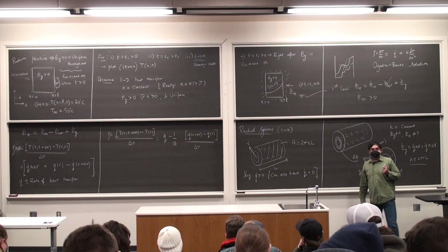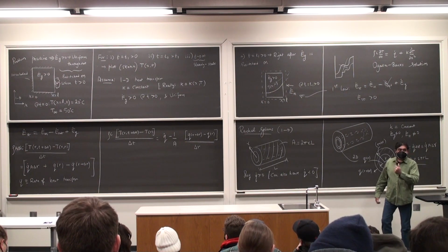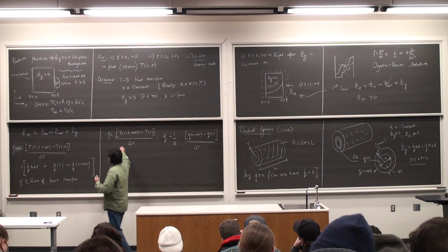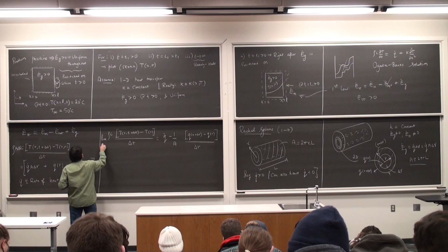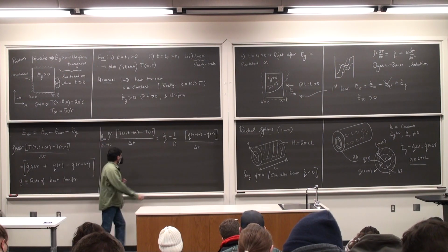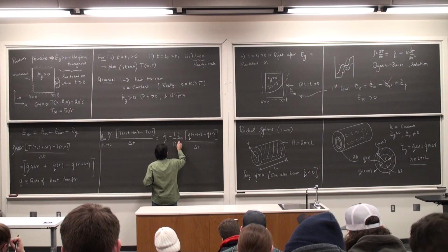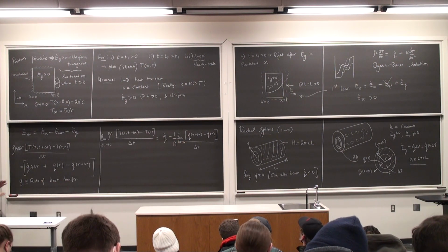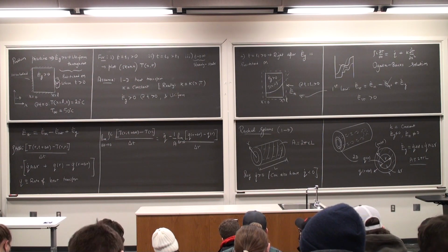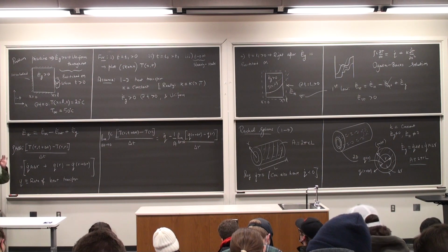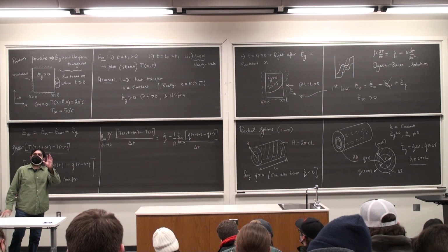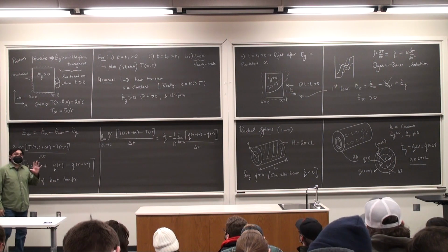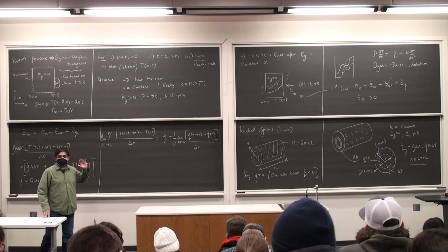I take the delta R, write it with the Q of R terms. I have to divide through by the area A as well, so I did that too. And I take the limit on both sides. Limit delta T tending to 0, limit delta R tending to 0 on both sides. And in the limit of very, very small infinitesimal time, in the limit of an infinitesimal ring element, these terms become partial derivatives. Why partial derivatives? Because they are a function of time and position.